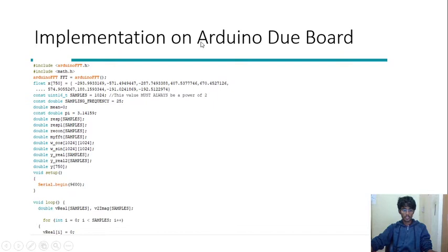Now here the message size is 750, but you can see we've taken the sample size as 1024. This is basically because while doing the recursion, at each step we'll be dividing the signal into two parts. That means we need a signal size which is a power of 2. Since we have 750 values over here, and the nearest power of 2 is 1024, we'll zero pad this signal. After the 750th value, we'll be zero padding until we get the size to be 1024.